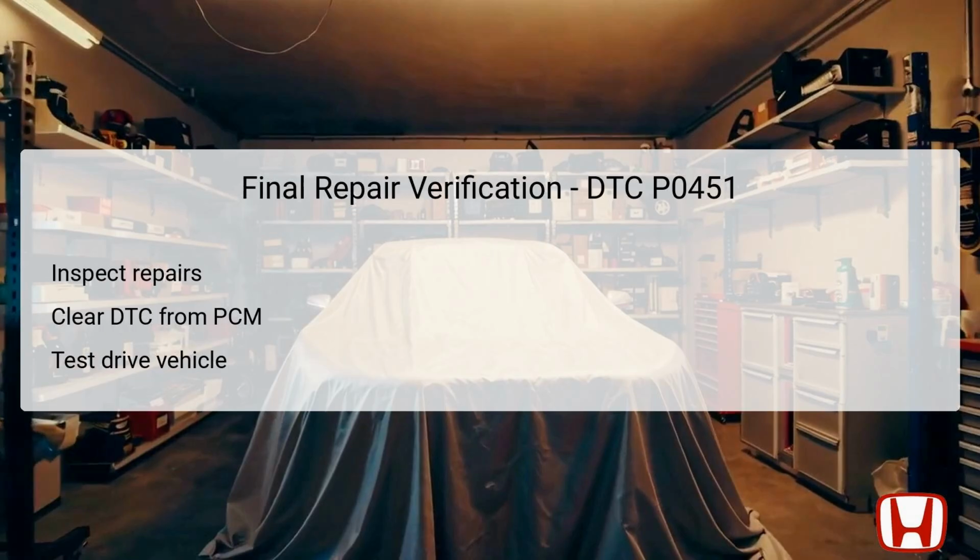After completing the necessary repairs associated with DTC P0451, final verification is essential to confirm the effectiveness of the work performed. This involves inspecting the repairs to ensure that all connections are secure and that the installed components function as intended. Following this inspection, clearing the DTC from the PCM ensures that any stored fault codes are removed, allowing for accurate monitoring of the system post-repair.